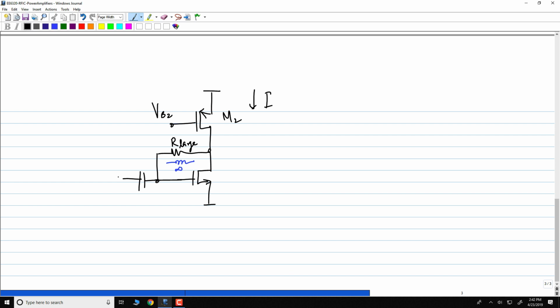So of course the signal comes in like this. Okay, I could do this. All of these things will bias the output voltage to, what will the output voltage be? What is the DC value of the drain? It is VGS1. Clearly, all of these things will bias it at VGS1. But this is not the best way of doing it, right?